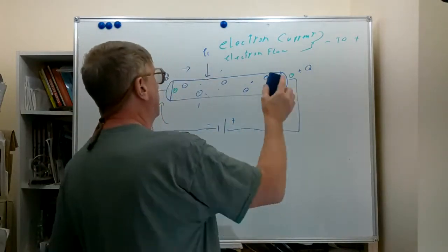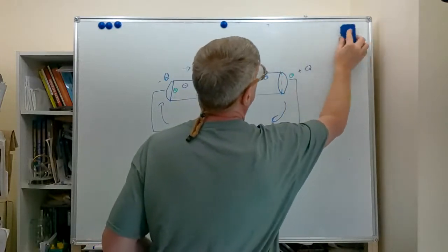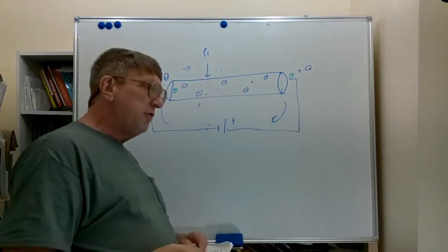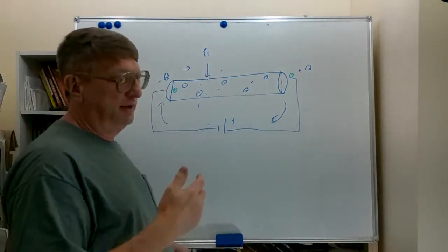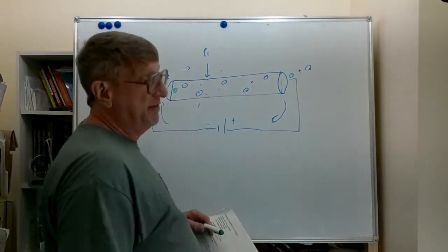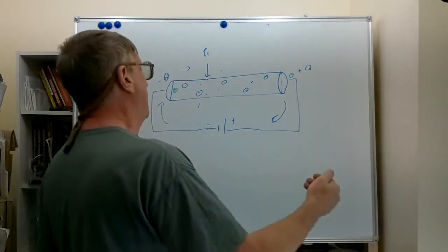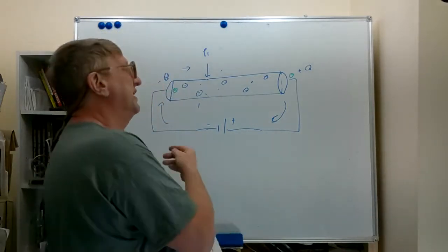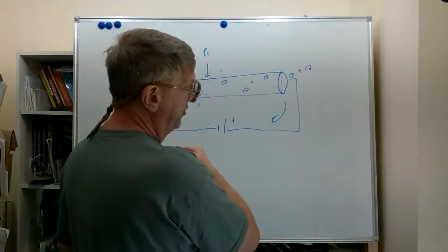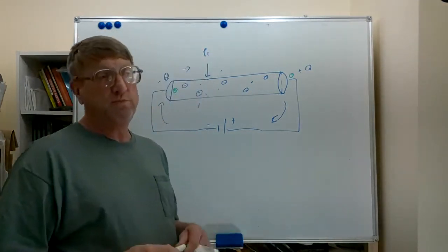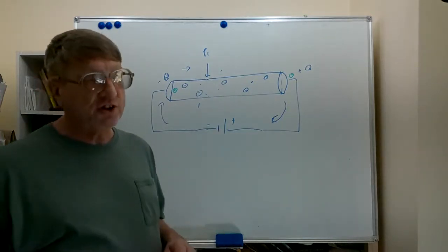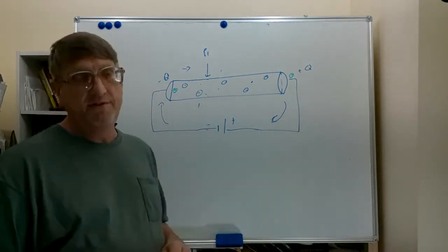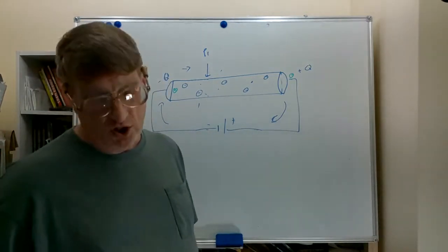In a wire, our current carriers are moving electrons, so we very often think of the electron currents going negative to positive. In solutions, as we pass current through an ionized solution, we have both negative and positive carriers, so we will see positive carriers going from the positive to negative terminal, and we'll see the negative ions, negative charge carriers, going from negative to positive. So positive to negative conventional current flow, as I talked about, is a real thing. It's just in electronics we usually think of electron flow and typically just call it current.